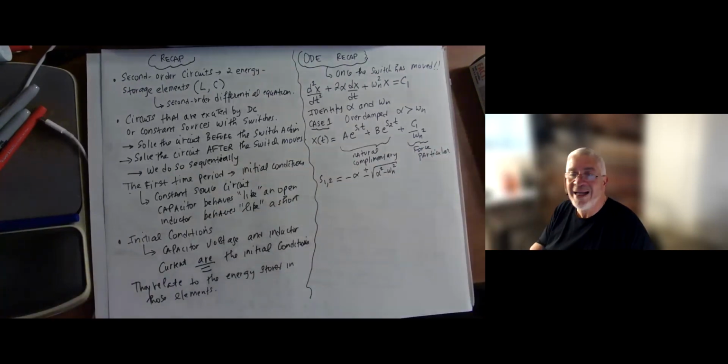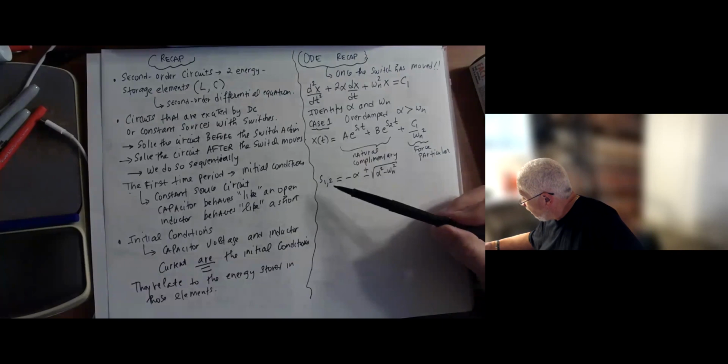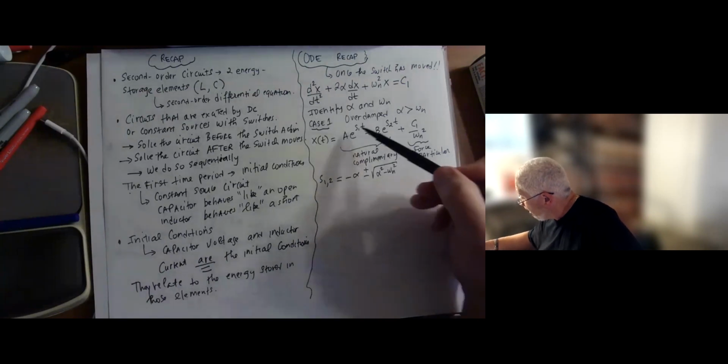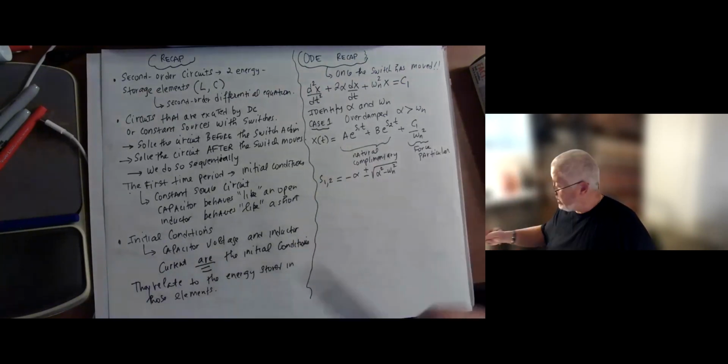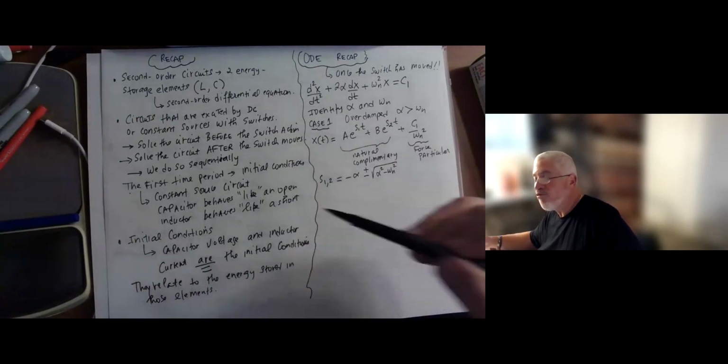So that is case one in terms of your Math 45 or differential equation content, and that is what we call the overdamped case. In the overdamped case, you get two real numbers for s1 and s2 that are negative but real. So you're looking at two exponents that are quickly dying out. That's why it's called overdamped.